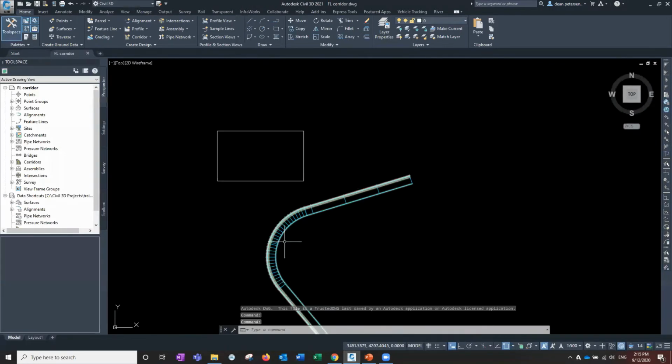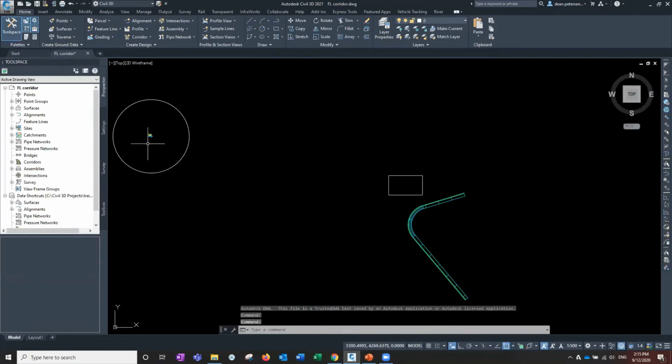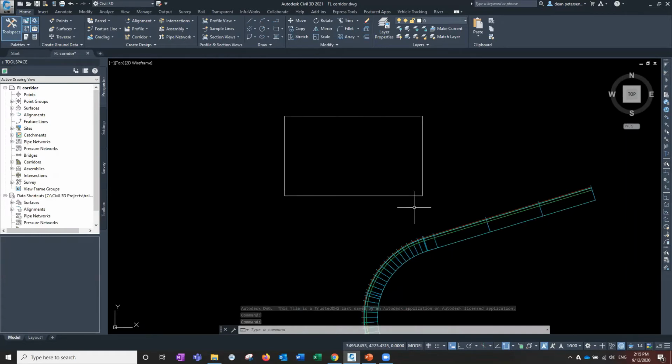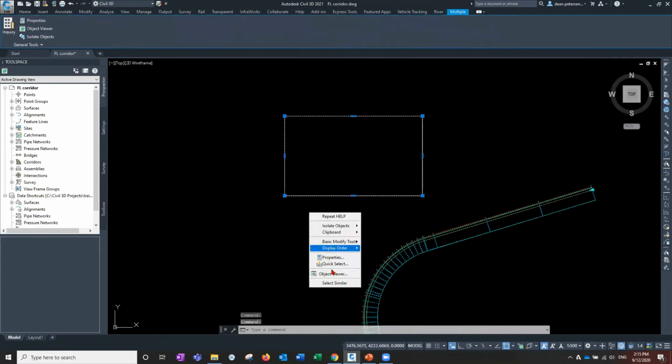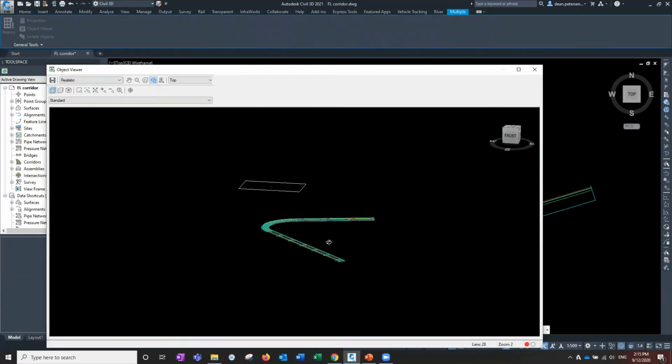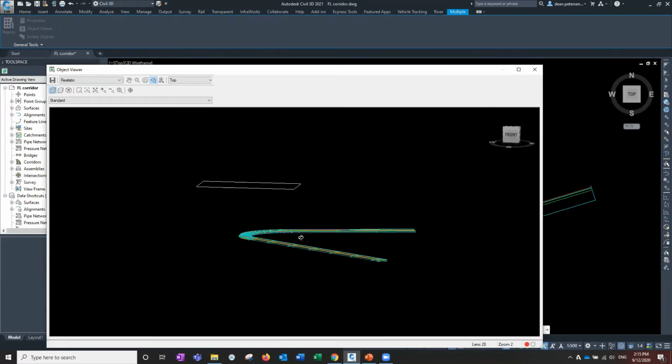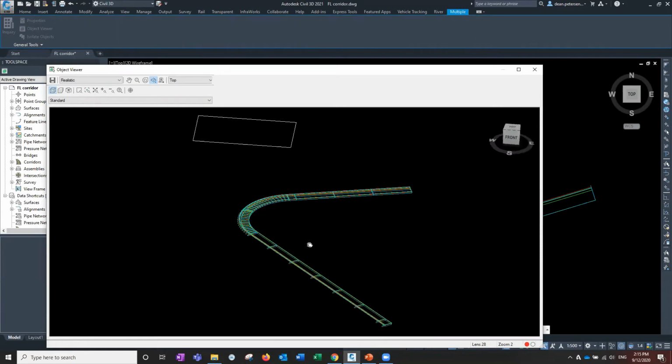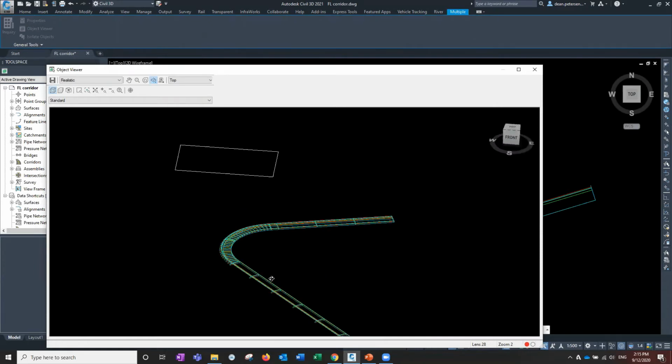All right, so this is a corridor running along a Featureline. My assembly is over here, and this is representative of maybe a building pad or something. They are at different elevations, but at the moment that corridor is just running horizontally at a particular elevation. The idea behind this is that the feature line that this corridor is running along, the vertexes of it, you can set the elevation relative to an object.